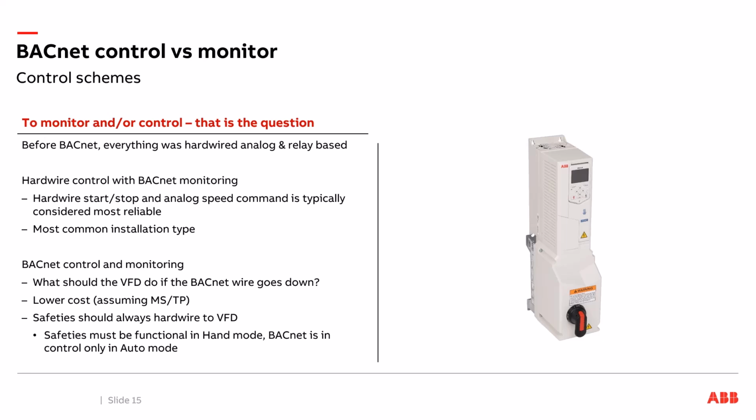I've seen too many installations where they run the safeties back to the building automation system, and then the building automation system just gives the drive a stop command if the safety opened up. Well, guess what? If that's a high static safety and there was an issue and it stopped the drive, now you run the risk of maintenance coming up and saying, people are complaining that it's too hot, I need to get this drive running, I don't know why it's not running. I'm going to put it in hand and force it to run up to full speed. Well, if there was an issue with airflow being blocked or VAVs weren't open, this is where you end up taking your square or rectangle ductwork, turning it into oval ductwork, or blowing out a seam. So it's very important to run your safeties back to the drive.